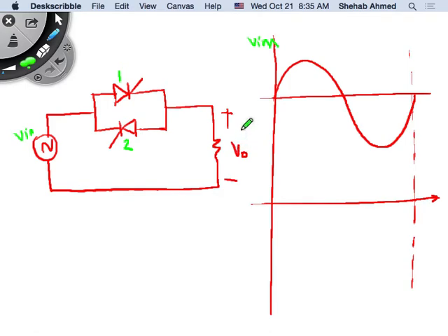So remember what we said about thyristors. For thyristors, the delay angle is from where the diode would have conducted, correct? So the diodes now are conducting from here, right? We agree? So that's where I'm going to start my delay angle alpha. In the first half cycle, I will add the delay angle alpha, and I will provide the firing signal to thyristor 1 here.